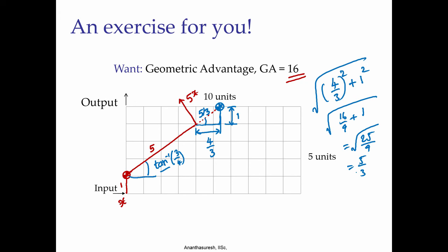And from here to here, that is the second stage amplification we get. If this point is moving like that, we have to join from here to there, okay. And that amplification, in that case, these are 5 units, 1, 2, 3, 4, 5, and then 1/3 there, 5 1/3, or it is 16 by 3.